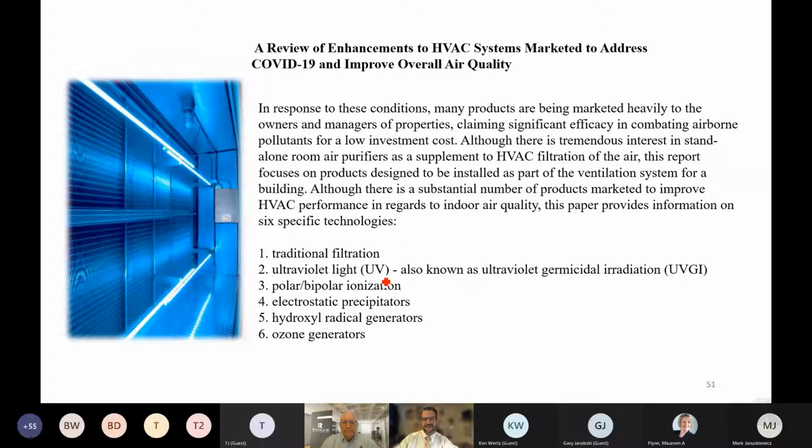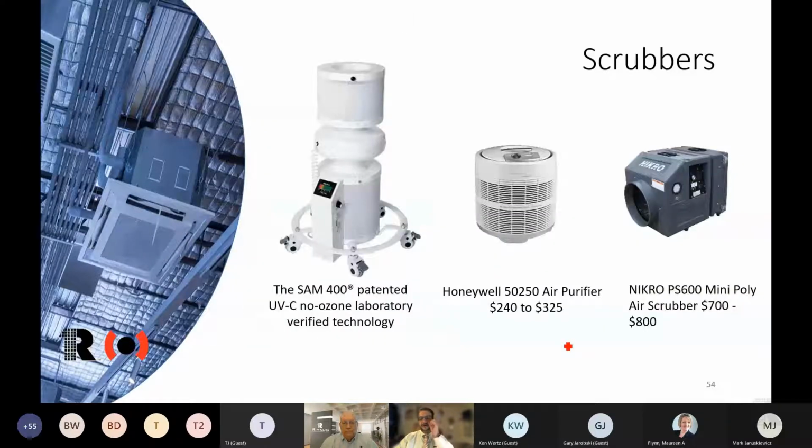Even the UV lights, it can be a big investment, and they're not going to last more than 16 months, in terms of their actual effectiveness. So, everything here has an upside and a downside. We do really want to be careful of using any ozone or ozone generating devices, because that's an irritant on the indoor environment.